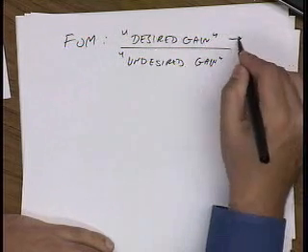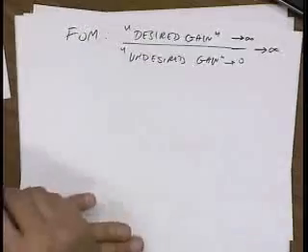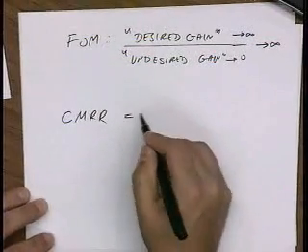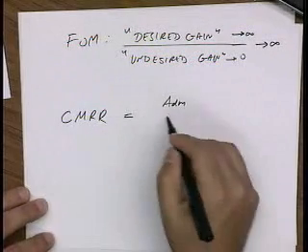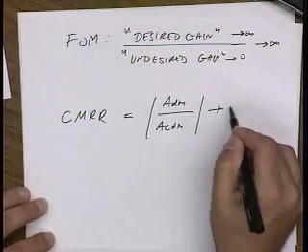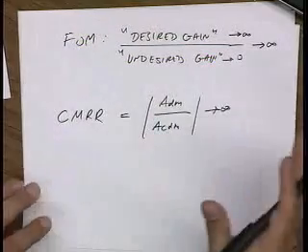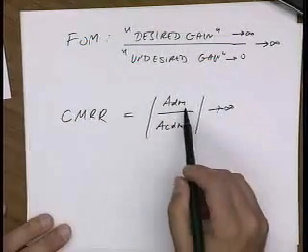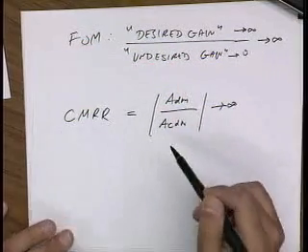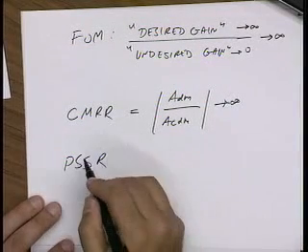And we want this to approach infinity, and we want this to approach 0, so we kind of get this double infinity. So this thing should really approach infinity. Okay. So common mode rejection ratio is the differential gain over the common mode to differential gain. And some textbooks will define this as ADM over ACM. Again, I don't really care about ADM over ACM. What I really care about is how much, what's really undesirable, is for a common mode signal to become a differential signal. Okay?